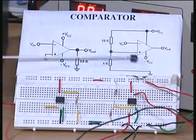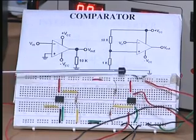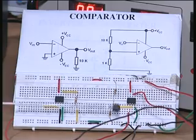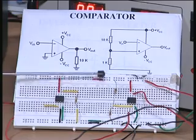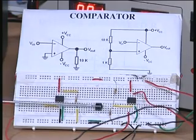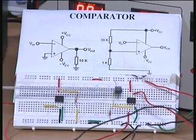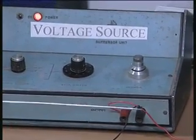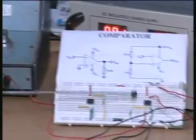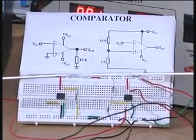Now the same circuit is wired here. You can see the 741, and pin 7 is connected to the rail voltage, the plus VCC, and the green wire corresponds to the minus VCC at pin number 4. I have the potential divider 10k and 1k here, which is connected to pin number 3, the non-inverting input, and to pin number 2 you see I have connected the millivolt source. This red line from the millivolt source is going to pin number 2 in the circuit, and the output is monitored by this red wire, which is connected to a multimeter.